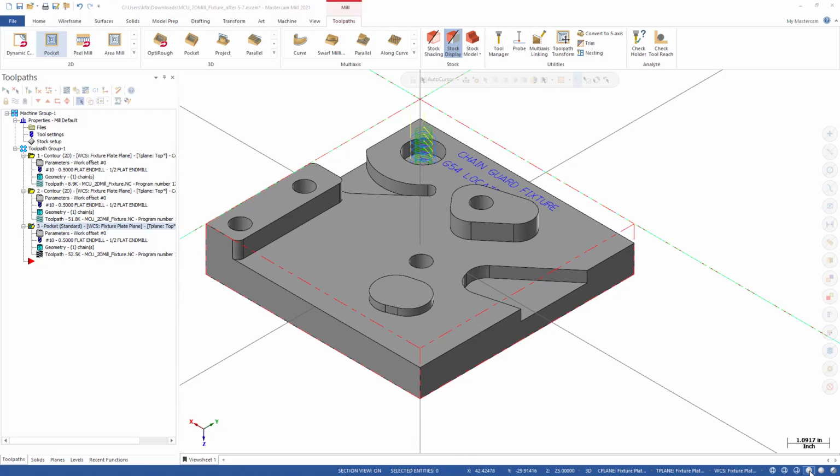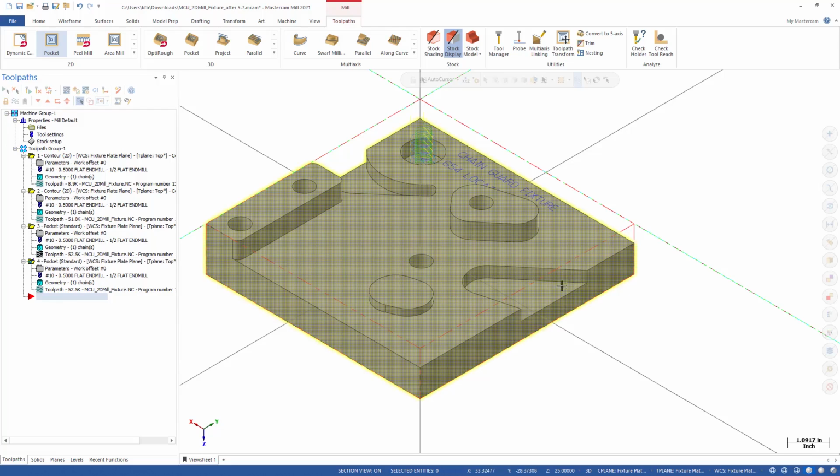Let's now take this pocketing toolpath and copy it like we did before. I'm going to copy afterwards, and we'll move my arrow down. And what I want to do is make adjustments to this toolpath. I actually want to set it up so it's an open pocket, and I want to use those parameters to machine a different area. For example, this area.